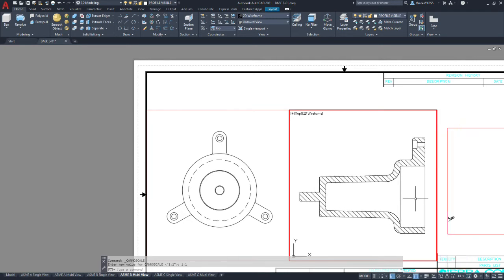On this assignment, we're not asking you to do any dimensions. So all you need to do is a cutting plane and have the section view look correct. Our section view plane is going to cut through the face here. So we've got this set up with our scales, and we need to align our views.